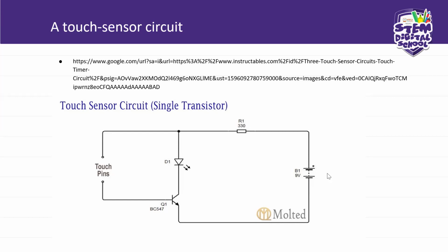If you have indicated your circuit like this in dots, you need to specify its value. The value is 9 volts. Battery 1 is 9 volts. Then another component that we see there is resistor 1. The value of resistor 1 is 330 ohms. Please, in your circuit, you must indicate the ohms. Okay, we do that in grade 9. And then you have your LED, that is diode 1, D is diode 1,